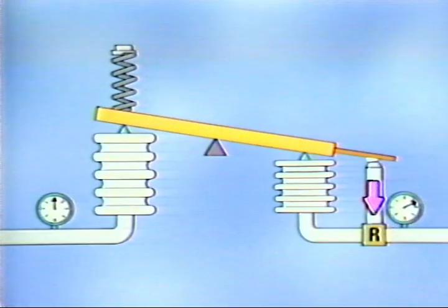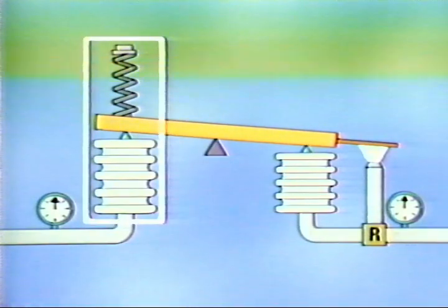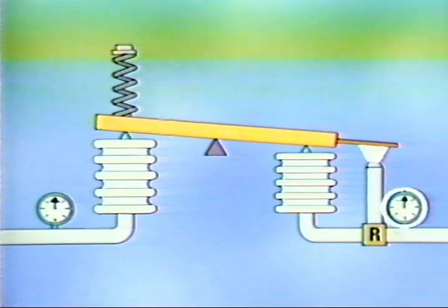The increase in output is supplied to the feedback bellows, which expands and brings the controller to a balanced condition that reflects the difference between input and set point. The controller's new output is proportional to its new input. So the controller has responded to an increase in the value of the process variable above set point by producing an output that is proportional to the increase.